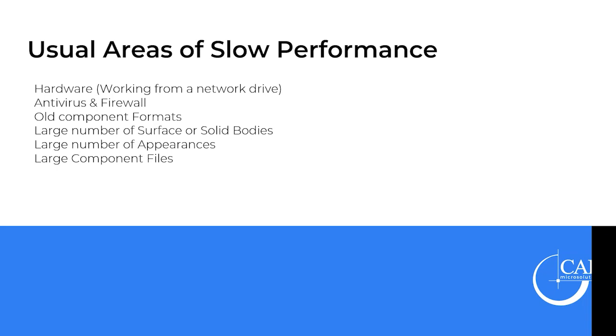This is something I have an active investigation with SOLIDWORKS on right now. We're trying to figure out why that is the case. I currently do not know the reason behind it, but it is something to look out for. I have an example which I can show in large designer view mode, an extreme example where instead of loading in 7 minutes, removing all the appearances makes it load in about 14 seconds. So quite a significant difference. And then last is large component files. Another thing to watch out for: if your part size is quite large, and especially if you're working over the network, it's going to take longer to load into memory.